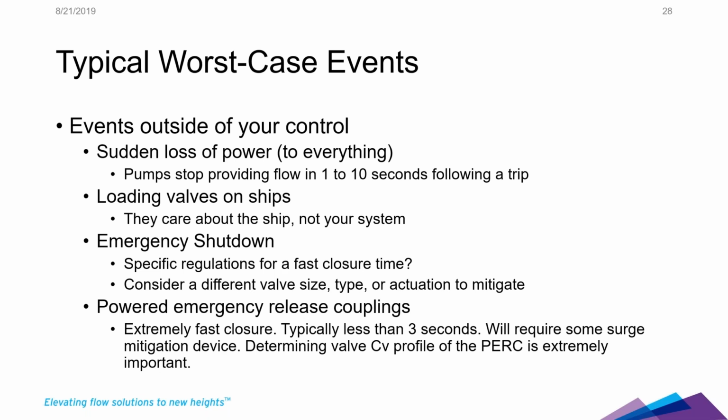And so that really extends out the last little bit of closure where maybe even large valves can throttle flow. But that depends. If you have really, really large valves, you might need to do something even different than that. You might need to change your throttling rate, and you might not be able to close it 80% of the way in the first 20% of time. You might not have an actuator that's powerful enough. You might not have a motor out there that's powerful enough. So you have to be creative with that. Things you might be able to do: multiple valves in parallel, close one valve fast, leave one valve open, maybe a smaller valve, and close that slowly.